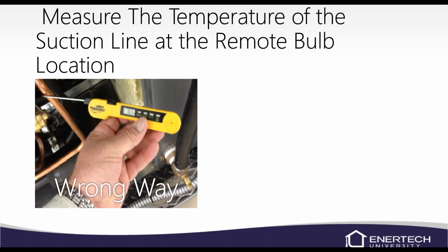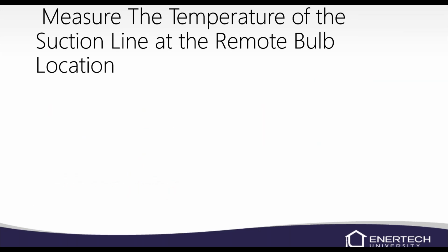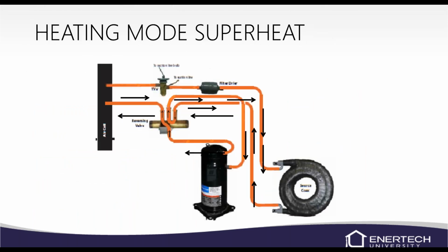Obviously, we don't want to use this type of temperature probe on a refrigerant line. They just don't work very well. I would recommend using the clamp-on style.